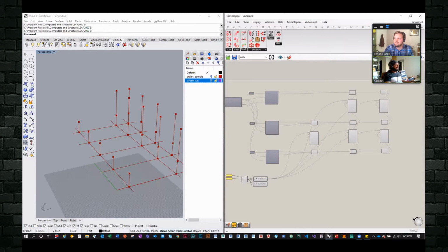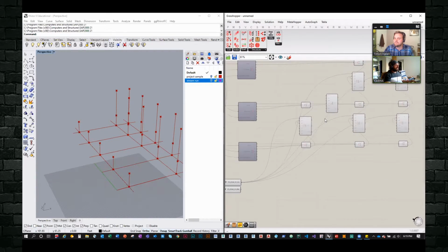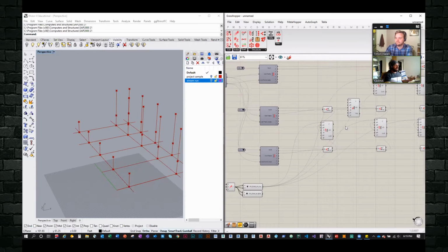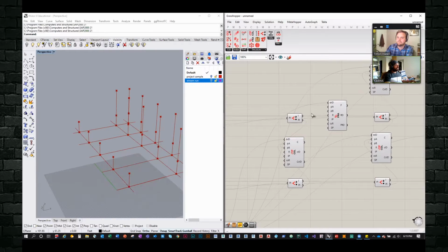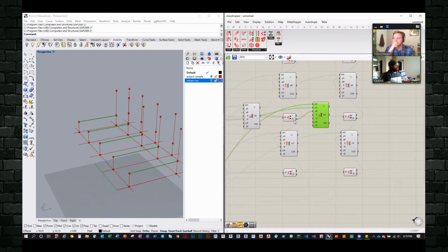And again, if I have another framing, I try to match it based on the Revit lingo. So this is create column and create framing. Revit distinguishes between column and framing, and this is how that develops. Again, this asks for a base index, and then a start point and an end point, and there goes my beam, and then you just repeat that over and over again.